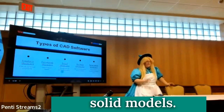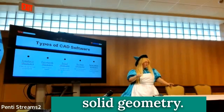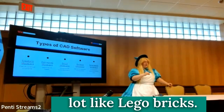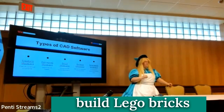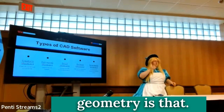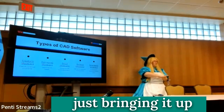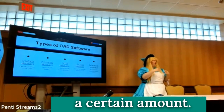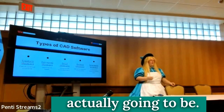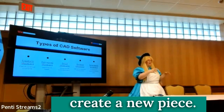Next, we have solid modelers. Solid modelers work on a principle known as constructive solid geometry. A great way to think of this is that it's a lot like Lego bricks if you could build Lego bricks as triangles. A lot of constructive geometry is that you define a shape and then you are just bringing it up a certain amount. This is also where you get stuff like Boolean commands, where you are actually going to be using the interactions between two pieces to create a new piece.